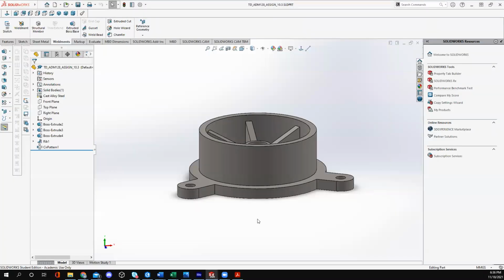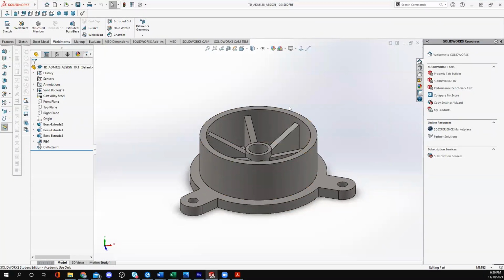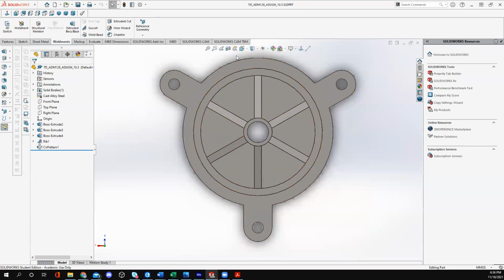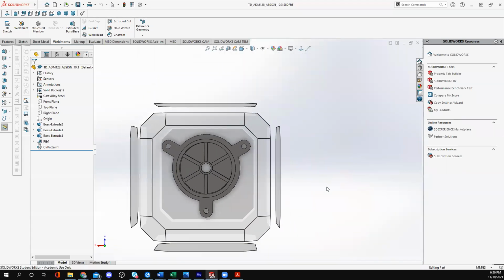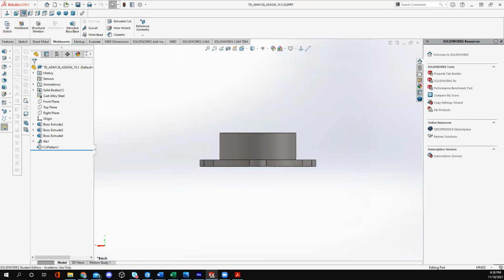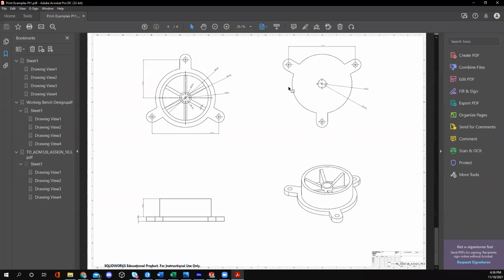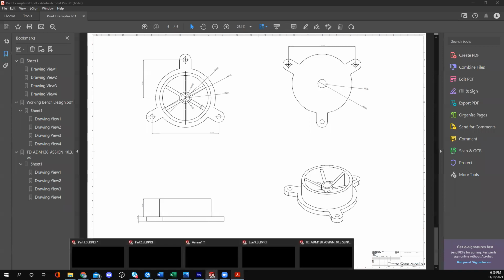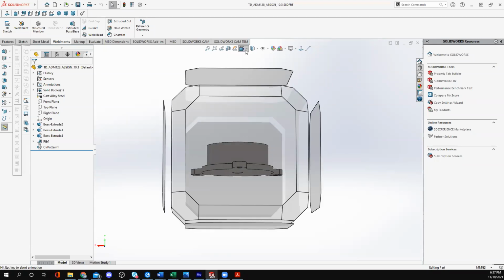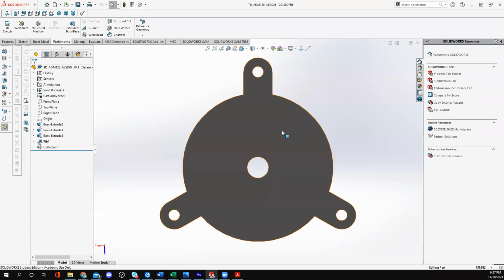But back into the SolidWorks drawing, this one, like I said, once again, we had a top down view. We had a side view, and then we had a bottom view. The bottom view is kind of necessary on this because it shows that the plate is solid. So this bottom view shows that it's not open up to the flange. And then we had an isometric view.